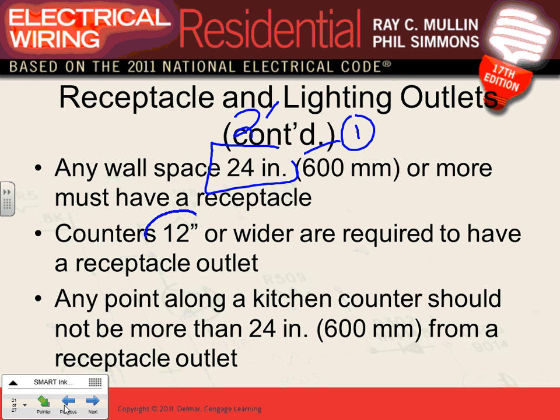In the countertop, if you have a space of 12 inches or more, you need 1 receptacle. Again, this is the countertop, and this is a habitable space. Everybody's okay with that? These kind of tiny little rules. A wall of 2 feet or more, 1 receptacle. That's where a designer becomes a good guy or gal.